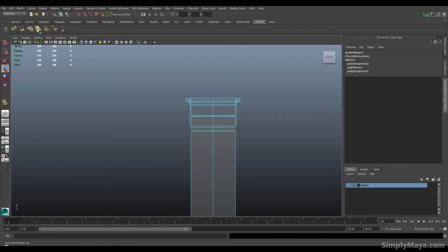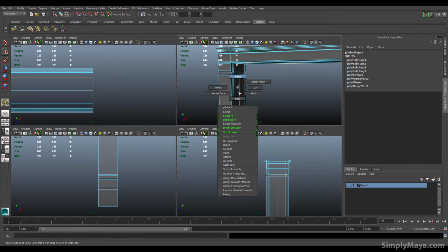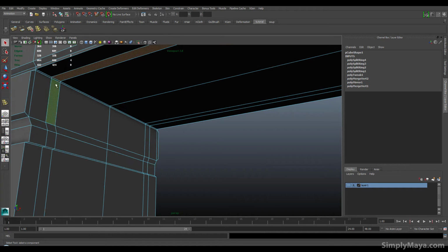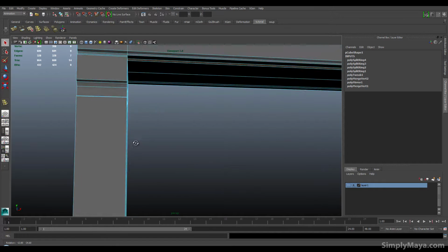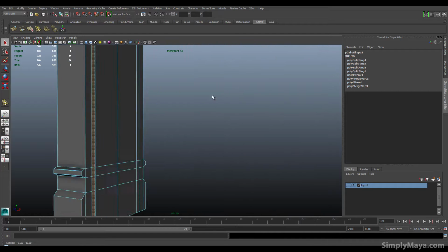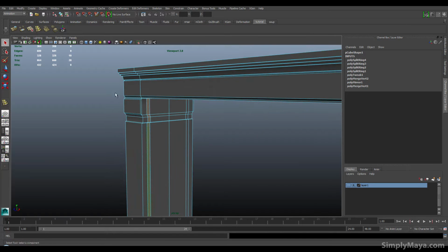We'll just use the split poly tool. Now it actually works. Now we've sorted out our geometry problem, and we'll make a little thin slice there, and approximately the same on the other side, little thin slice there. Now I need to go into here and select all of these faces, and make sure you get them all, otherwise you're going to end up in a bit of a mess. Okay, and that seems to be just about everything.